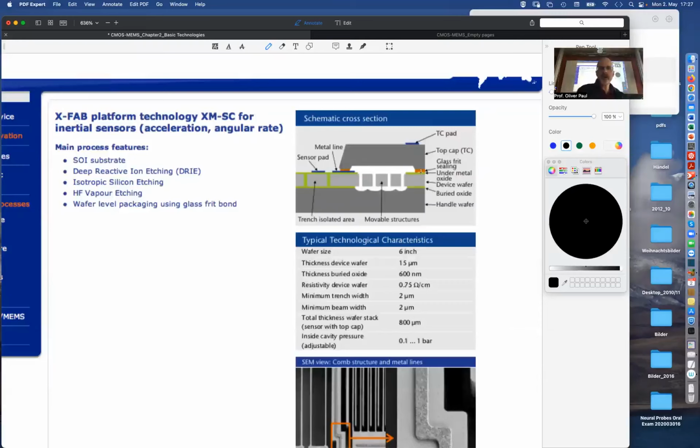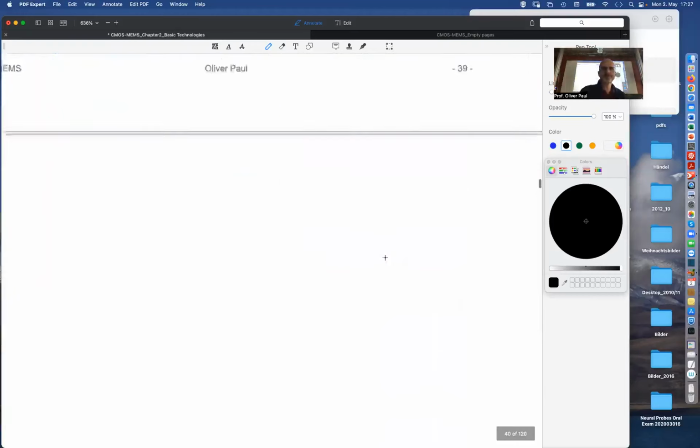And this region is then packaged by an additional top cap, an additional silicon structure enclosing some delicate micromechanical structures, vibrating beams, forming capacitors that are able to measure the acceleration of the structure in the plane, for instance, to do an accelerometer or a gyro, as we will see in the last chapter of this lecture later during the semester.